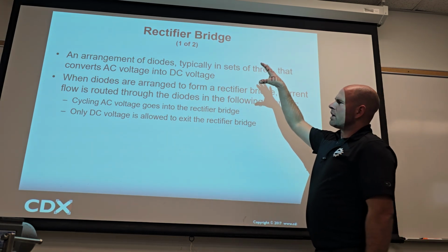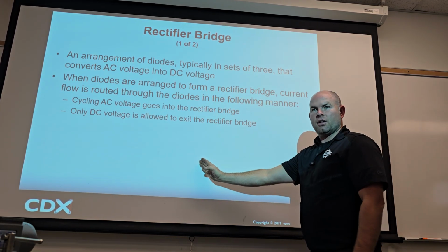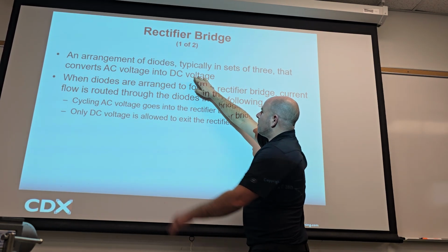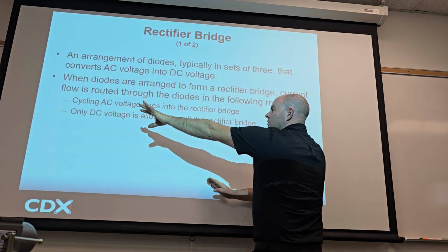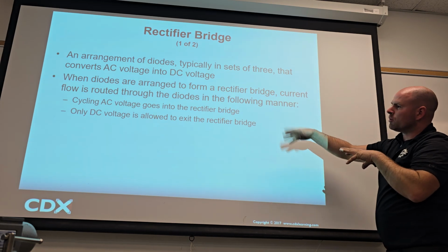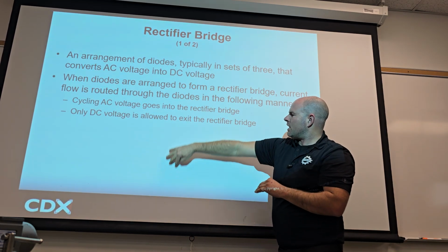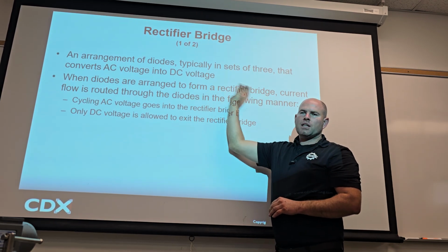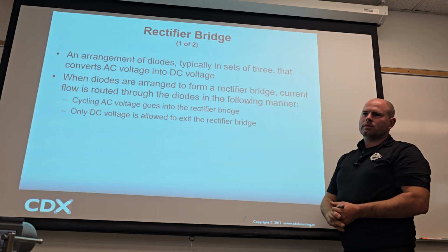So we can use this rectifier bridge, and because remember the AC goes up and down, we could use those Zener diodes and say, like, when the AC is up, let's let that push through the Zener diode, but once it drops down, don't. And then if you have a fast enough frequency, it'll basically just skim the tops, right? If you had the peaks and the valleys, it would only allow flow at the peaks, and that's how you might get your 13.6 volts, right?